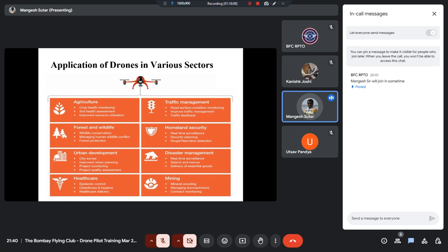Here, when you are having a drone, you have data. You will be capturing it in the form of some information. It could be photographs or other inputs, thermal, lidar, hyperspectral, multispectral. What not kind of sensors you can use, and you will have the data. And the frequency of capturing data is also very high, so you can monitor progress. Let's say in a civil project, like you're building a building, every month you can fly a drone and take stock of what is happening, how much progress we have made.